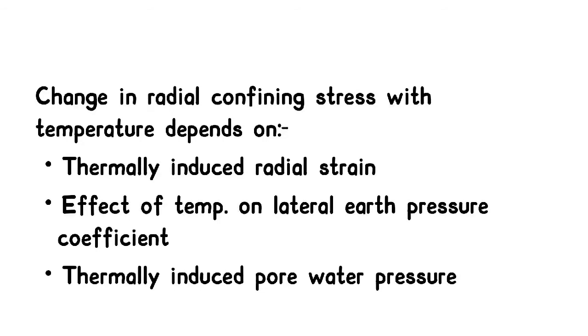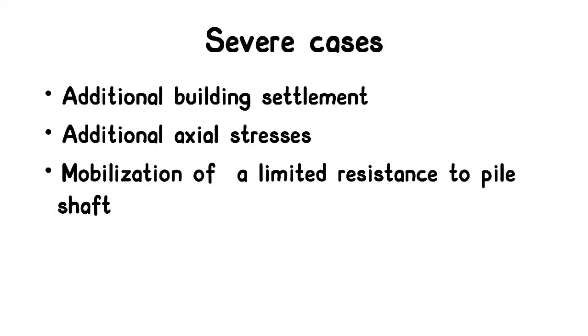That is, if it is a saturated soil and you are heating up the pile, the water in the pores will get heated up, which basically creates a pore water pressure. This pore water pressure is called the thermally induced pore water pressure.